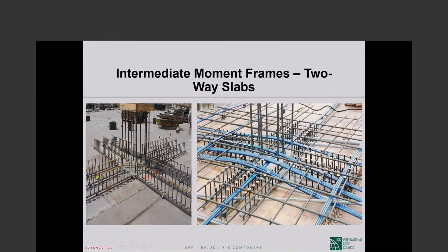That's what everybody provides. And I know plenty of California engineers who will just throw this in. They don't try to figure out if they can get exemption, this and that. This is cheap insurance. This is the cheapest insurance you can buy for a flat plate column frame in a high seismic design category. Okay, I will go as far as that.